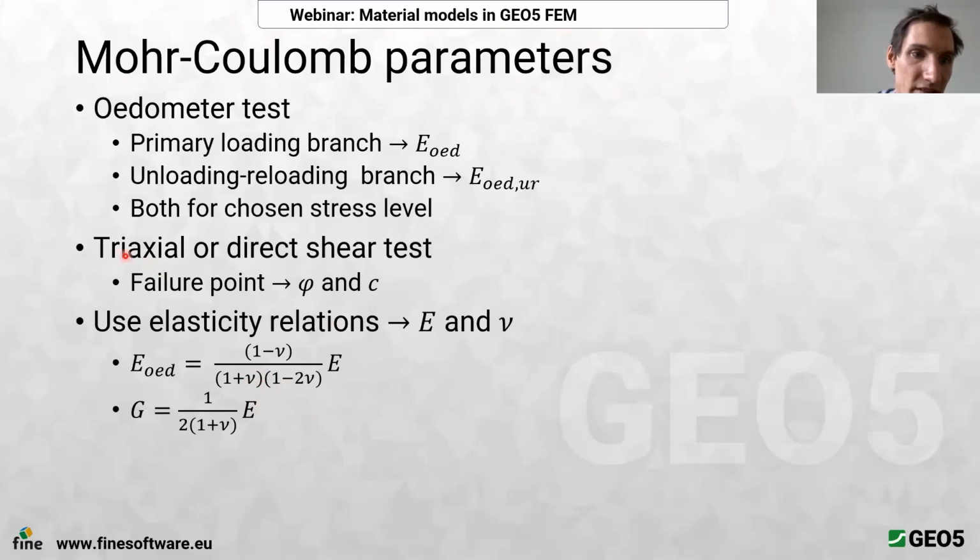But if you did the triaxial test, you can obtain the shear modulus and use the oedometric modulus and shear modulus to calculate Young's modulus and Poisson ratio.